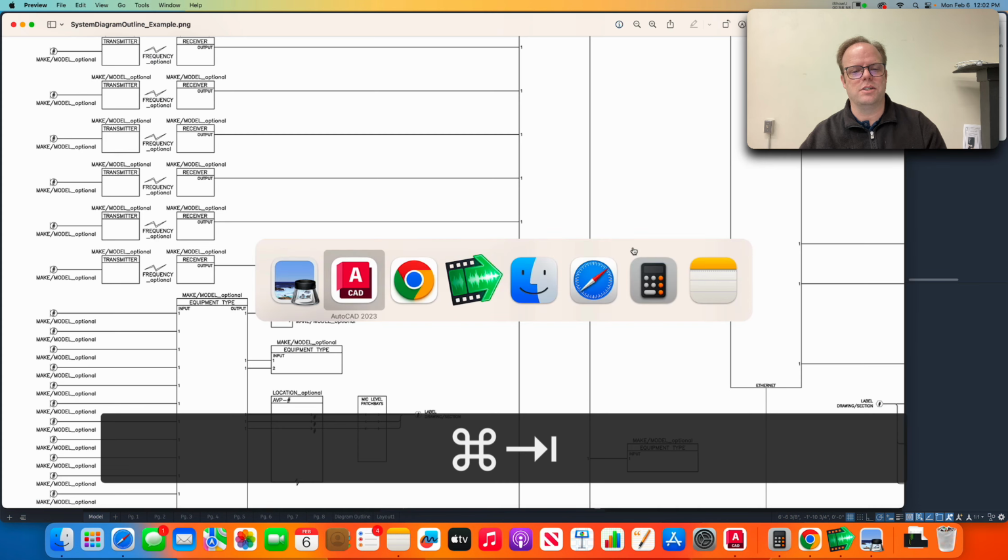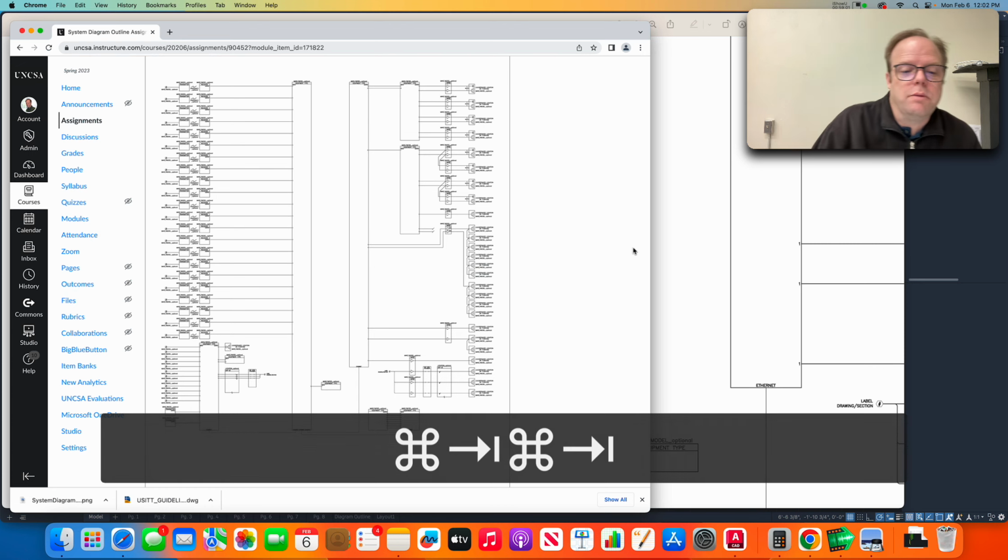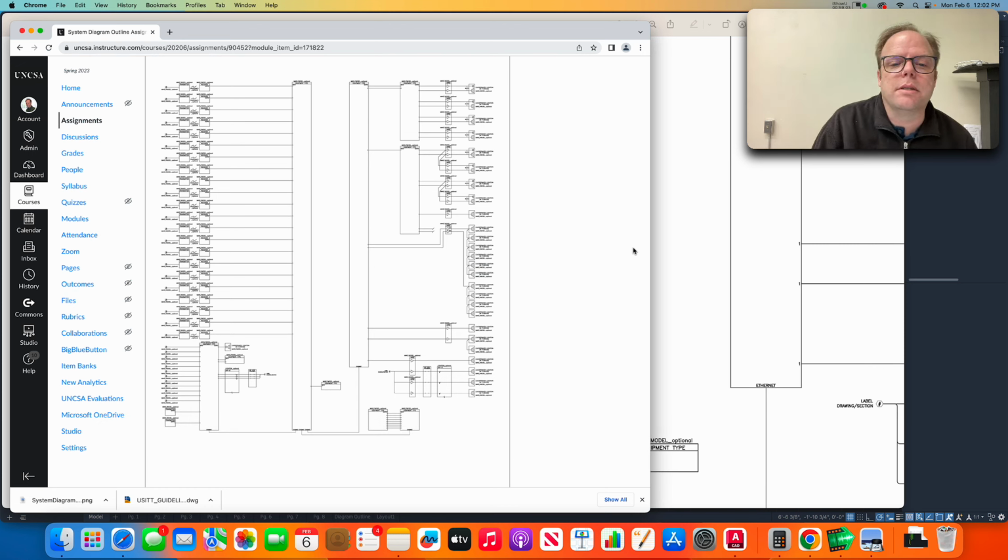So that is your assignment. It's really not going to take you as long as you might think. It'll go pretty quick once you get into a rhythm. Just resist the temptation to use other methods. You really can do this whole thing with copy, move, extend, trim, mirror. All right, we've got 45 minutes or so you can keep working, and I'm happy to help you with whatever you're stuck on. Just holler out.